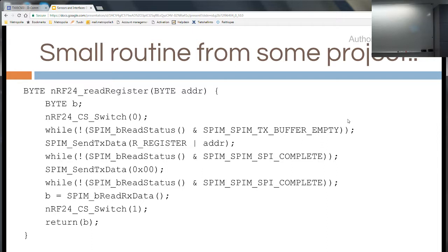Okay. And read register max with the address. Good. Okay, again, it waits until the SPI module is ready. Send another data. If there was something received from the device, it should have been read here. So when the SPI is complete, then you basically should have read that byte here. But well, this is just sending a few bytes there, so it's the next sends there. Then well, that's basically an empty payload.